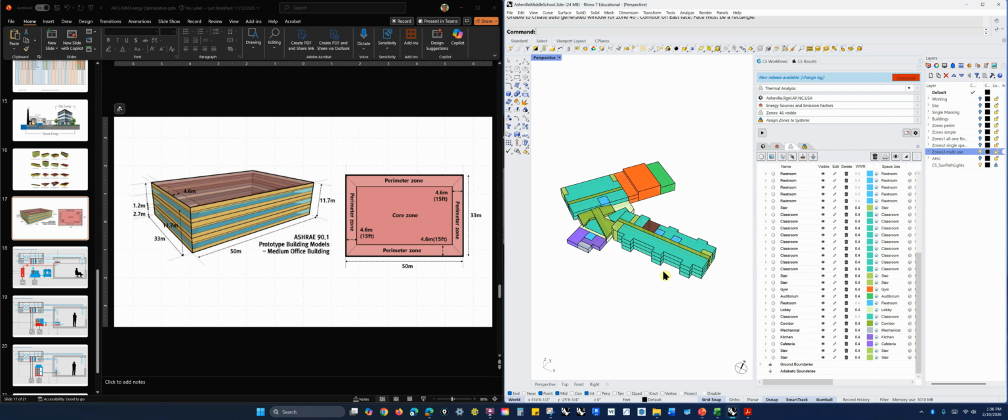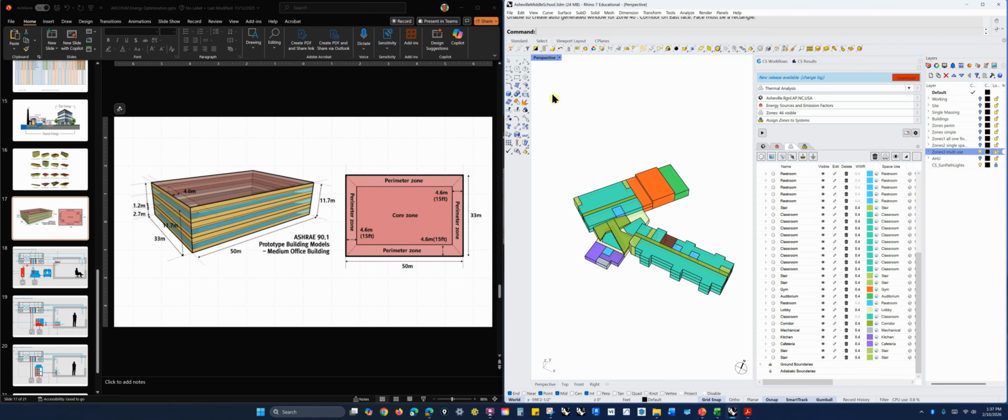Now, again, if I were to go and try to apply different mechanical systems to all these, I think it's going to break the model. I could try it, and there's nothing wrong with trying it. Always save. If you're crashing out or if it's taking forever to run, just stop it. If you totally crash, just close, open again. If you've just saved it, then it's not a problem. I always, before I run a simulation, try to remember to save it. But I've also got my saving settings so they save pretty often, and there is a place on your hard drive where crashed models go, and they're saved to the most recent, at least, setting time.